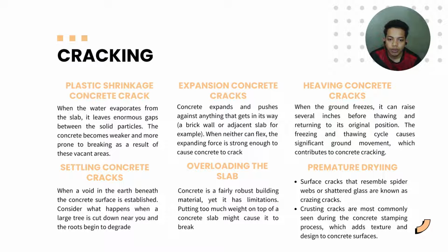For overloading the slab, concrete is a fairly robust building material, yet it has limitations. Putting too much weight on top of the concrete slab might cause it to break. And the last cause of cracking is premature drying.